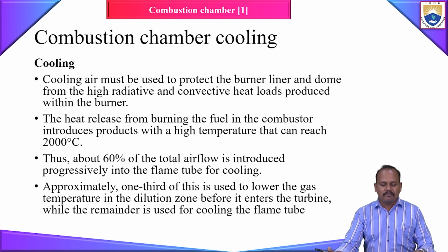You see, of the high pressure air from your compressor, almost 60% is used for cooling of the flame tube alone. Let's say 10 kg of air is coming inside your combustion chamber; in that you need hardly 4 kg for the complete combustion.